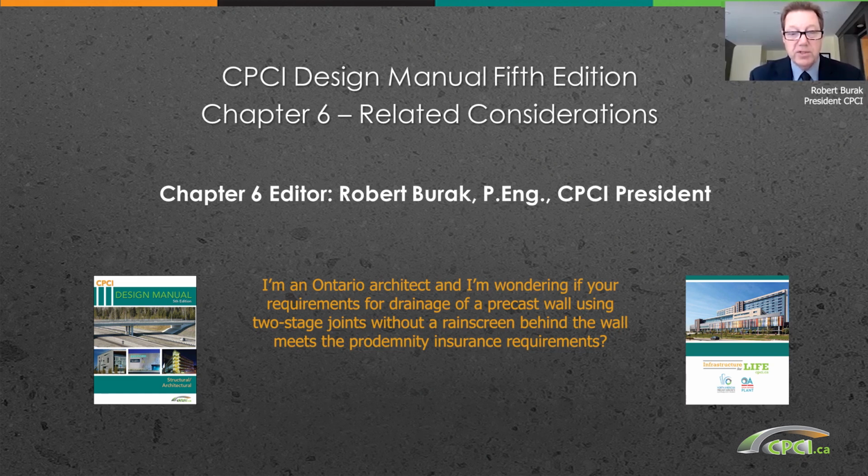So I'd say this is a really good question, and we often receive it. The pro-indemnity insurance coverage does provide specific exclusions for a number of different assemblies, and this does include precast concrete. For precast concrete, they specifically call out walls designed and constructed as drain systems utilizing 2-stage drainage joints, or two-stage drain joints. So yes, you would be covered. This exception was recently added to address this kind of question, which is quite common, because there were some problems with rain leakage and condensation caused by designers attempting to create drainage areas and gaps behind the precast.